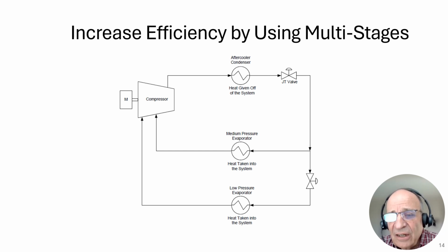In this case, let's say originally we want the car air conditioner to be operating at 35 degrees Fahrenheit. So we operate this system at 45 psi absolute, and we get 35-degree R134A coming through here. And we also take a slipstream of that and go to even lower pressure. In this case, we're going down to 20 psi absolute. And that 20 psi equates to 0 degrees Fahrenheit.